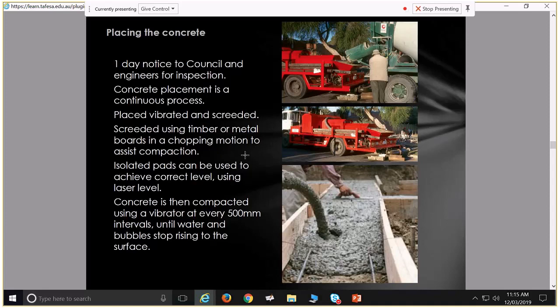Concreters start really early in the morning. They'll be on site at 6:30, 7 o'clock or something like that, or sometimes even earlier. Now, the EPA say that you're not allowed to start on site before 7:30 in the morning, and certainly if you've got a concrete pump going bonk, bonk, bonk at 7 o'clock in a residential area, you will be a very unpopular person. But to get that concrete pour happening at that time of the morning is a fantastic thing, because your steel